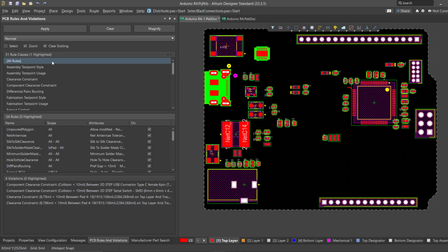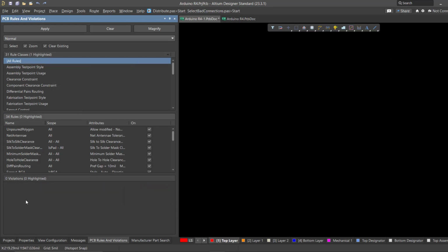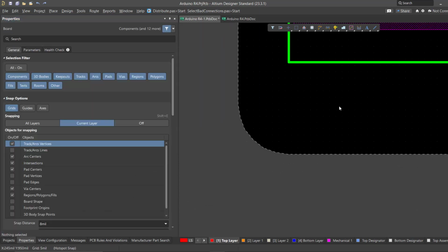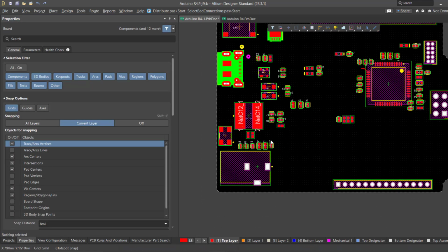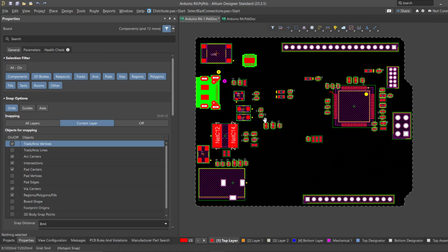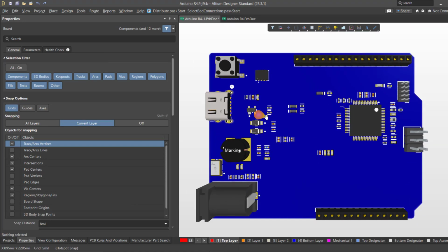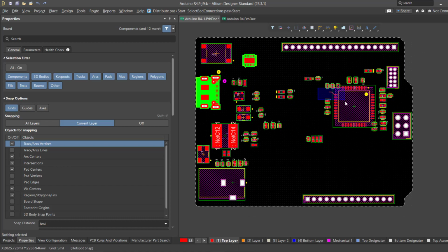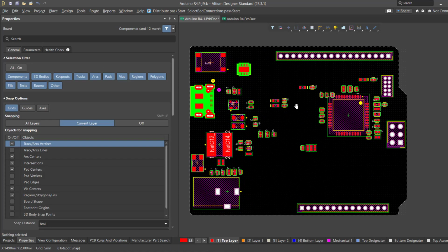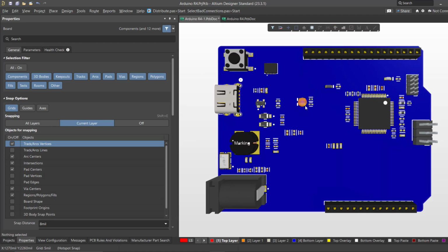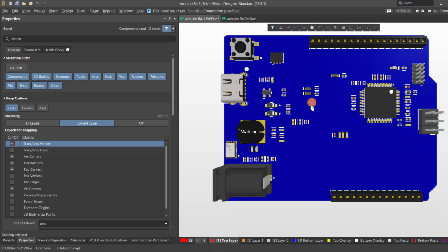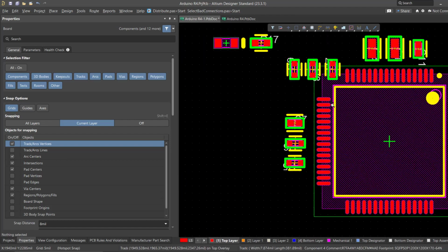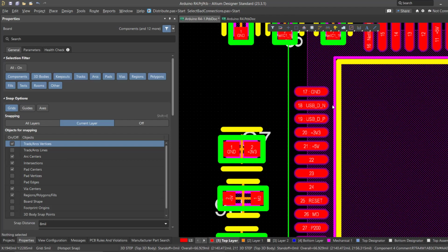Next, we need to add a via fan-out in the components. Adding a via fan-out is crucial for efficient signal routing in PCBs with components featuring a high pin count. It simplifies the routing process, reducing congestion on the top and bottom layer of the board. This not only aids in completing the design but also enhances signal integrity by providing shorter and more direct pathways for traces.